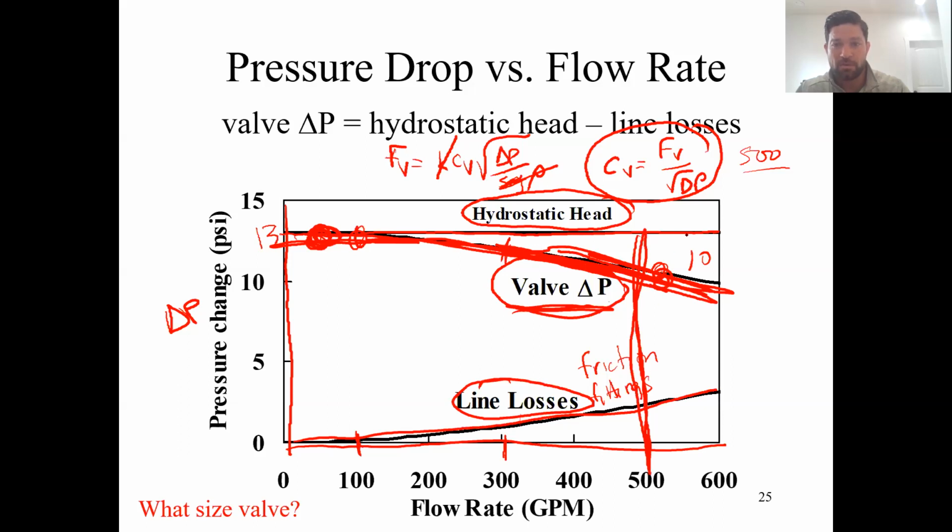The pressure drop up here is, what is it? About 10 at 500, maybe 11. Let's just say that it's 9. So I can take the square root of 9, so I have 500 divided by 3. So what's 500 divided by 3? 166, I think. Anyone want to confirm? Yep. About that? Yeah, that's right. 166 and 2/3.